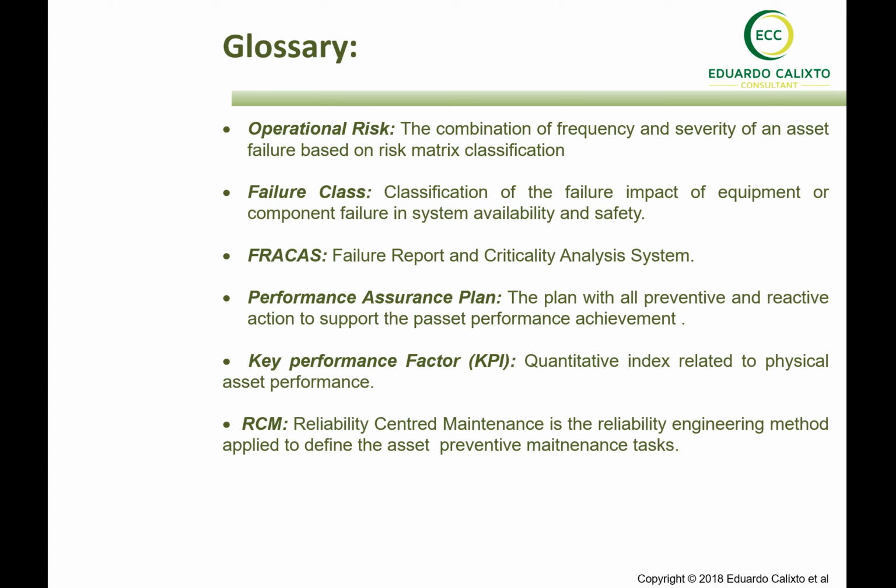Okay, FRACAS, the failure report and critical analysis system. We already discussed a little bit about it, and FRACAS is important, as we already discussed and demonstrated during this training. That's a very important database, and it gets all the incidents, the failures, and also the issues and the equipment degradation detected by inspection and non-destructive tests. Then FRACAS gets all such information, and together with the maintenance schedule defined mostly in CMMS or SAP, we encompass the asset management database.